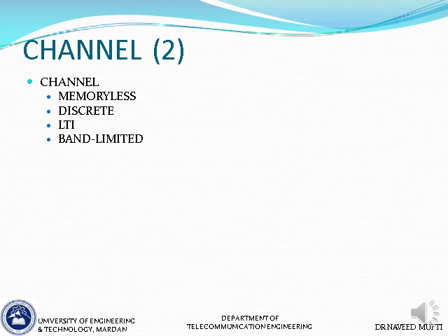So a band limited channel will disperse or spread a pulse waveform passing through it. That's what you have to remember, because a pulse signal has an infinite bandwidth requirement and channels mostly are band limited. So when a pulse passes through a channel which is by definition band limited, the pulse will spread or disperse.